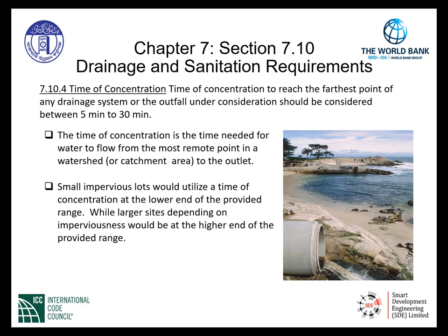It will then travel through the gutter, down the downspout or the downpipe. From there, it will terminate onto a sidewalk. It will then follow the slope of the sidewalk onto an adjacent parking lot. It will follow the slope of the parking lot to a ditch, where it will leave the building site. The duration of time that the raindrop took to travel that distance is the time of concentration.